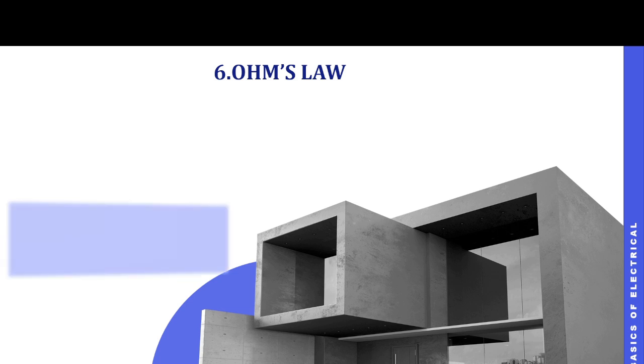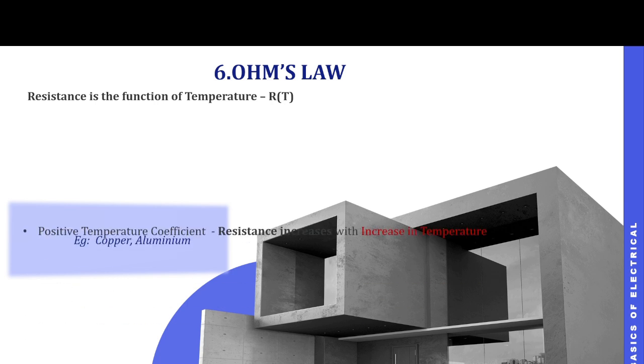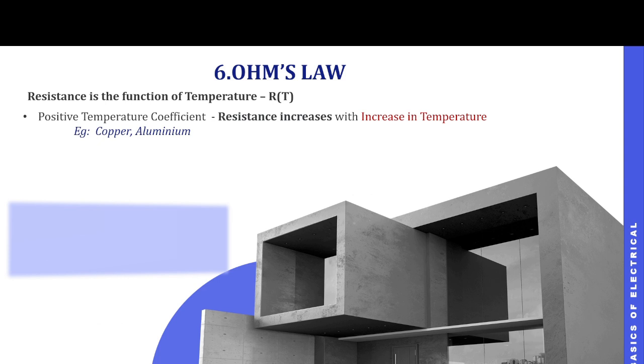First, we already know resistance is a function of temperature. That means in some cases, when the temperature increases, resistance will increase. In other cases, when the temperature increases, resistance will decrease. Normally in copper and aluminum conductors, when the temperature increases, resistance will increase. Similarly, when temperature reduces, resistance will reduce. That type of